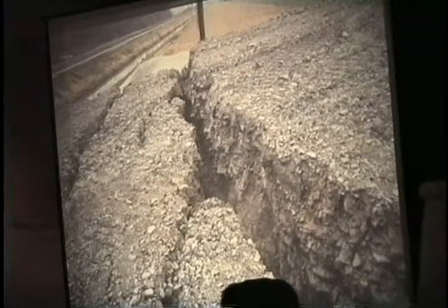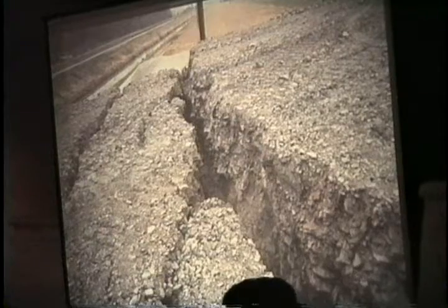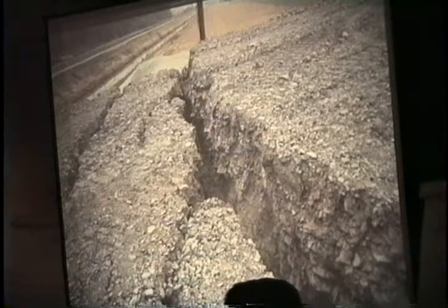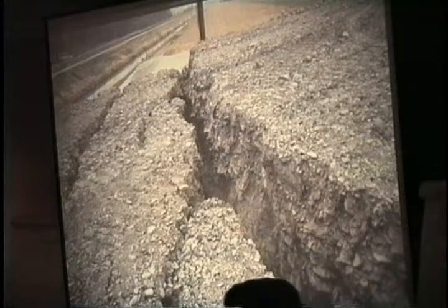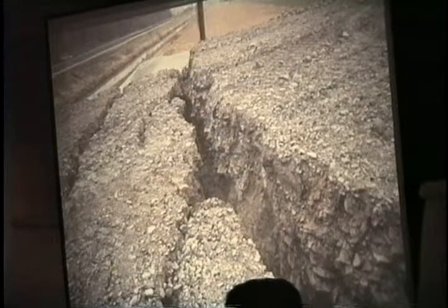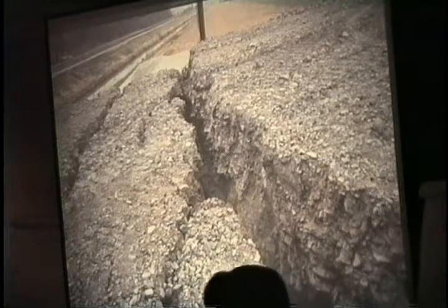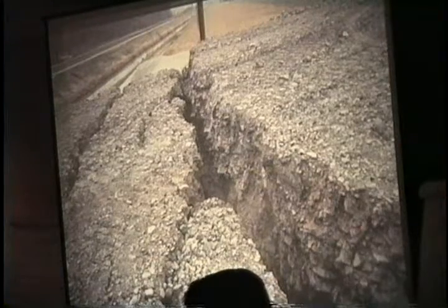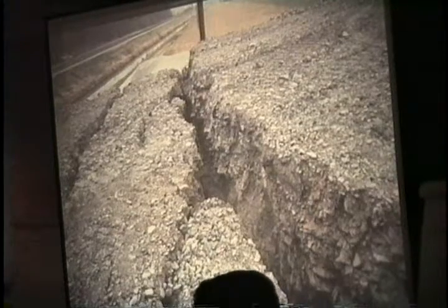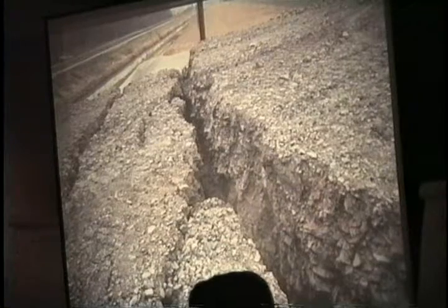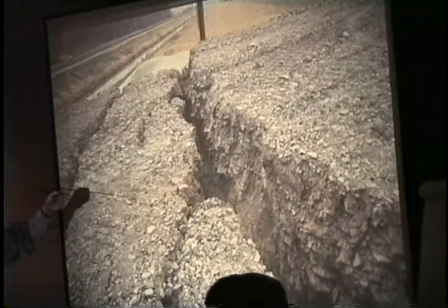All right, so my suggestion to put the scrapers in there, move the material and put it in front of the wall. What would that have done? You're unloading the driving forces, and by putting the same material in front of the wall, what am I adding? I'm adding toe resistance. Balance it. Okay, so we're trying to balance it. Unload this driving force and put a load in front. That would have saved all this.